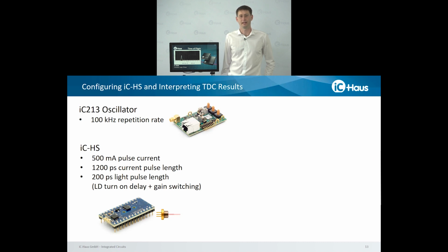you apply to it. So for detecting it with a conventional photodiode, we need as much light or brightness as possible. So we just go for the 500 milliampere pulse current that it can deliver.